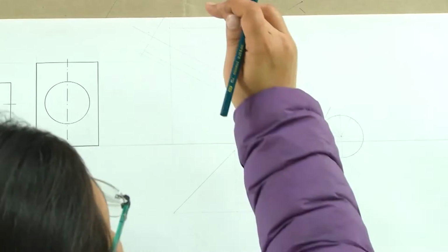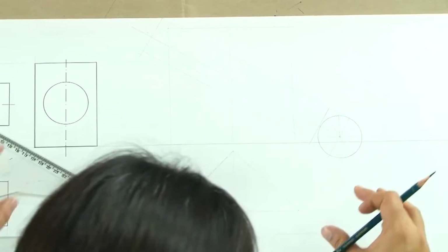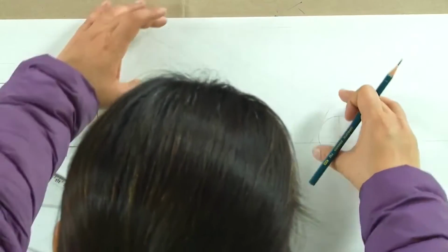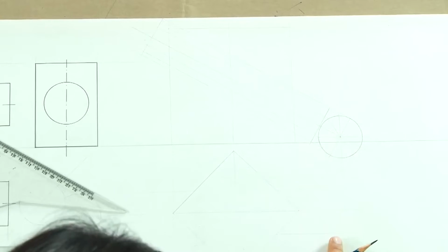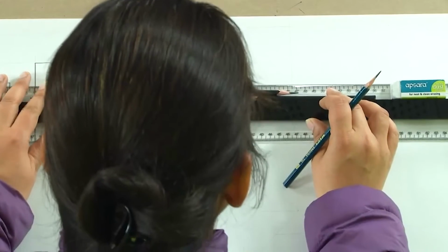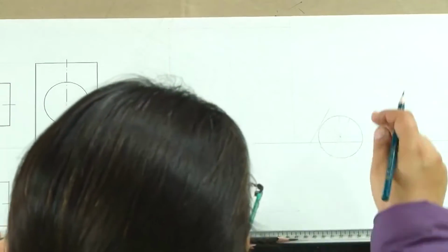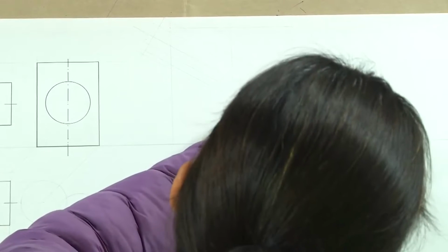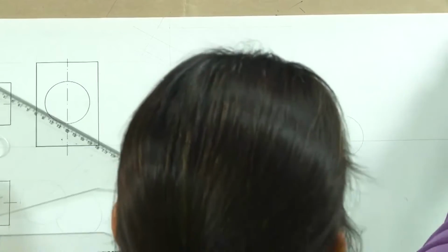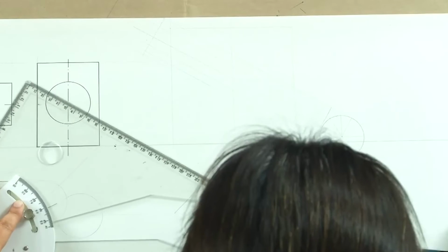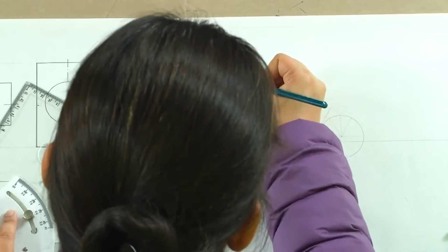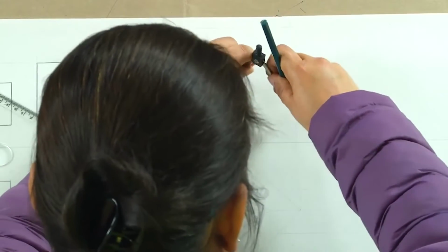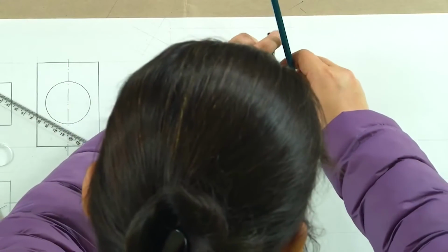What we know is where each of these points is getting cut. So, this is the circle, and if I were to make it initially parallel originally here and then rotate it, we will also get the same 12 points in the bottom. What we were having originally was a line like this and these 12 points coming, and the same were being projected back. So, originally it was like this. Let us make another circle for a better reference here. What we have is that this point remains the same and all other points are rotating about the center, which is where the axis has rotated itself.